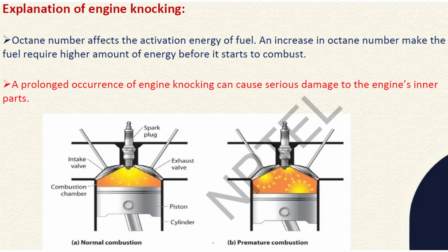Explanation of engine knocking. Octane number affects the activation energy of fuel. An increase in octane number makes the fuel require a higher amount of energy before it starts to combust. Prolonged occurrence of engine knocking can cause serious damage to the engine's inner parts.